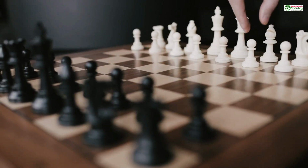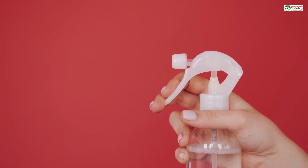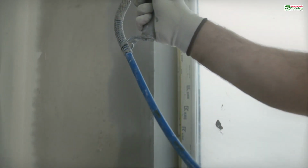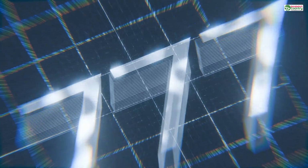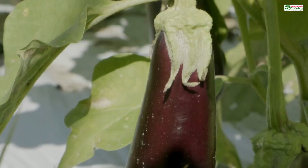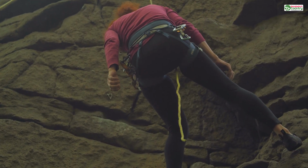For a 0.4mm nozzle, that gives you a range from 0.1 to 0.3mm. This is why these numbers are so common. It's the range where the machine operates reliably and produces consistent results. Going below that range is possible with specialized equipment, and going above it can lead to sloppy, weak prints. So when you choose standard quality, you're really just telling the service to use their best practice setting for their standard hardware, which is almost always a 0.4mm nozzle printing at a 0.2mm layer height.